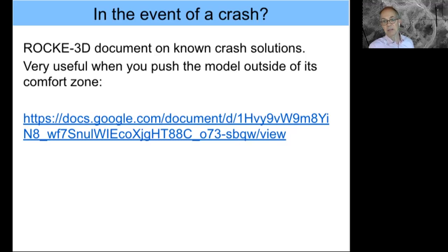So it may run a factor of 2 slower or a factor of 4 slower, but if you're near the end of what you think the model is, if you think the model is approaching equilibrium toward the end, then it may be worthwhile for you to consider just changing the dynamical time step and keep the model marching forward. So take a look at those if you have problems with the model crashing.